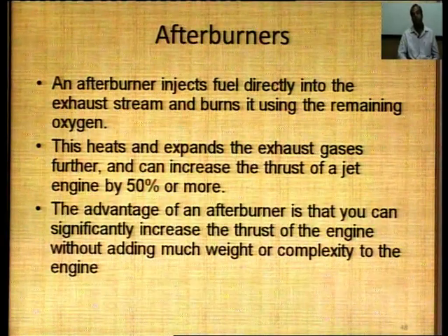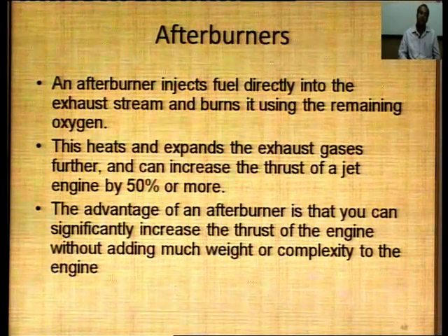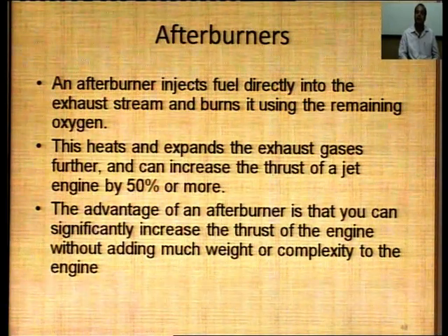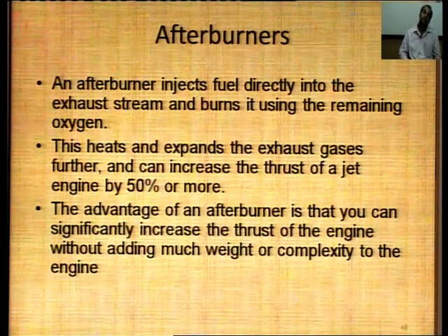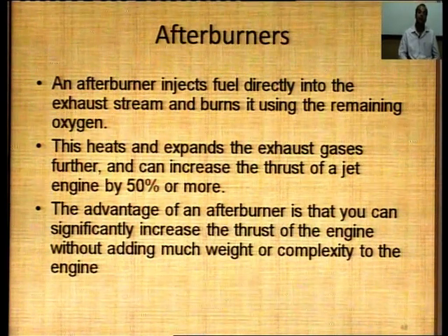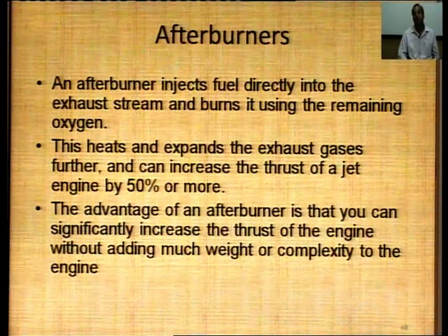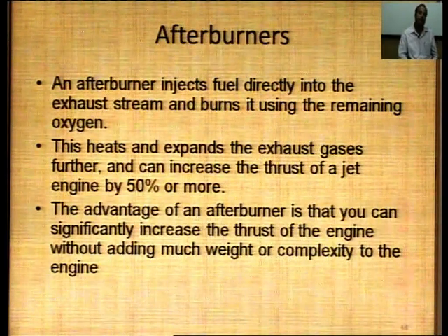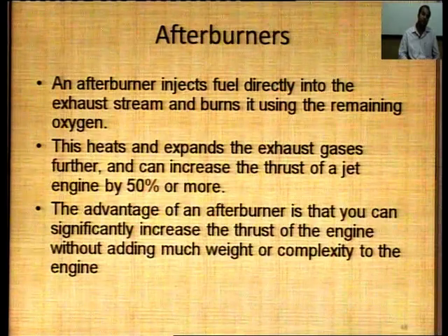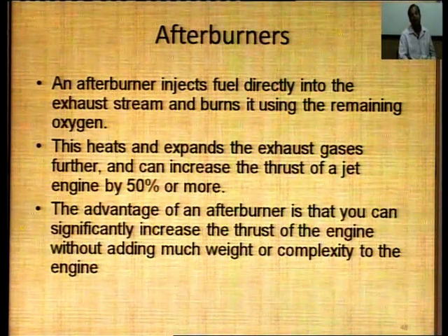Second, this heats and expands the exhaust gases further and can increase the thrust of the jet engine by 50% or more. These are some more advantages. The next advantage of the afterburner is that you can significantly increase the thrust of the engine without adding much weight or complexity to the engine.